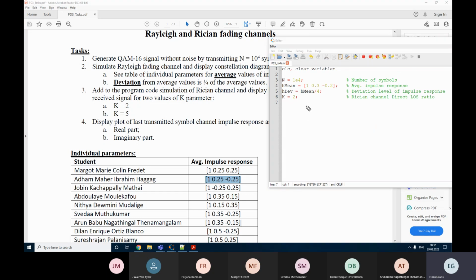What we are going to do now is generate the real part as either plus minus 1 or plus minus 3, and generate the imaginary part the same way. So the result of random generation should be any one of these 4 numbers only. No other numbers should be generated this way, yes. And then we are going to make a quadrature amplitude modulated signal just by making the real part plus the imaginary unit multiplied with the imaginary part, right? And the result will be already a modulated signal. So we basically generate already 2 pulse amplitude modulated signals.